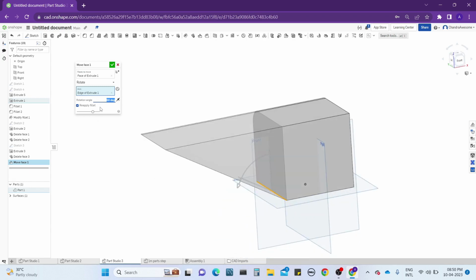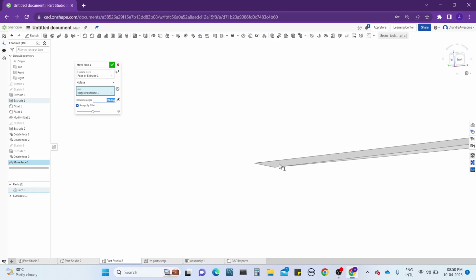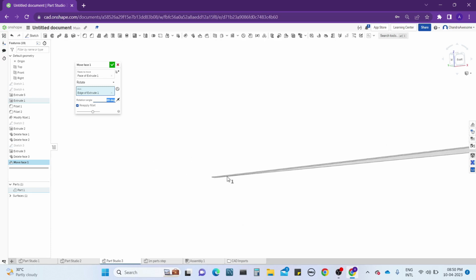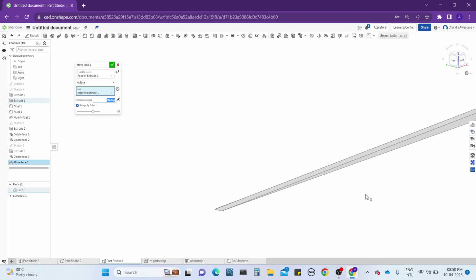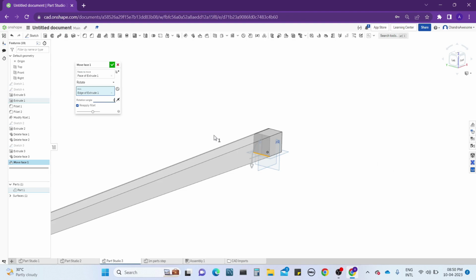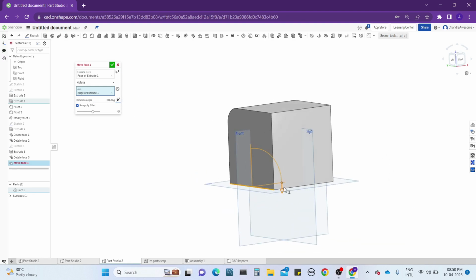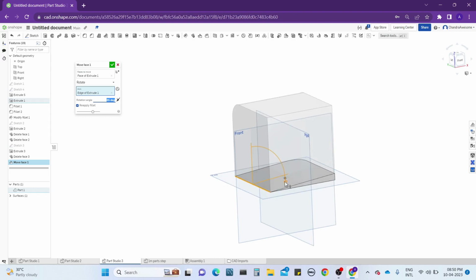As per the degrees, it will work until 89 degrees, but it will not work at 90 degrees because you can see here the tip will go to zero, and when it comes to zero geometry you can't see the part, and it will say over constraint. See, this means over constraint. That is the difference, guys. Okay, like this also you can remove.